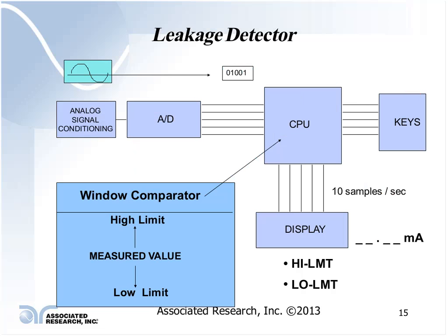This shows a little bit more about the leakage detector. Again, using a window comparator, we are allowed to set up a high limit based upon what your product would normally draw, and a low limit, again, based upon what your product would normally draw. Now, some standards will tell you to set your trip setting using a 120 k ohm resistor based upon your test voltage. Some of them will tell you to set your trip point to a specific current level, like 60335 is an example.